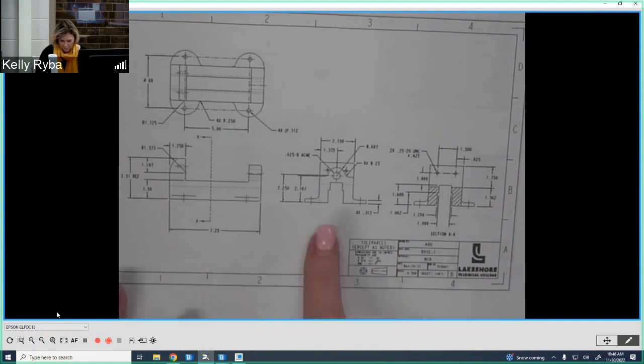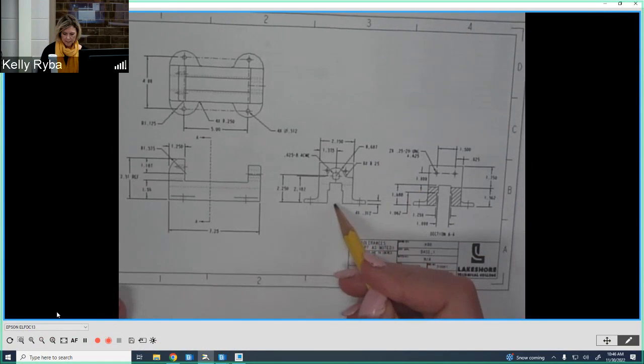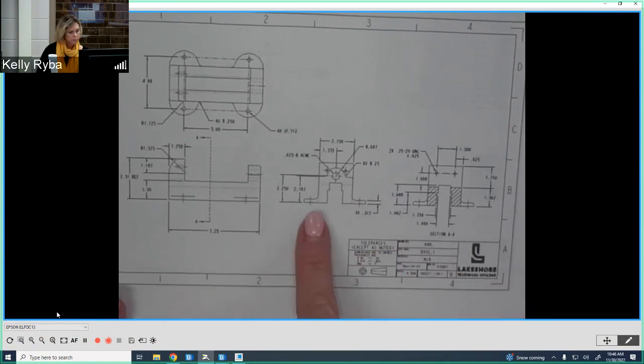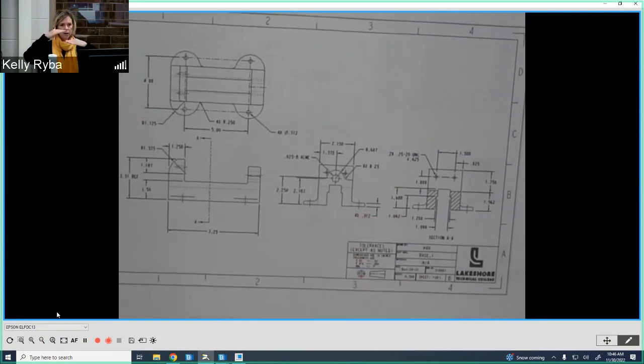And we actually have, you know, two continuous surfaces here, all right? So they're separated by this little distance here. So if we would put flatness, for instance, on one side, it would only be flat on that one area. And if we would put another one on the other side, they could be like this, all right? So we want them all in the same plane. So that means that we have to use profile for this, and profile of a surface, okay? So surface profile.